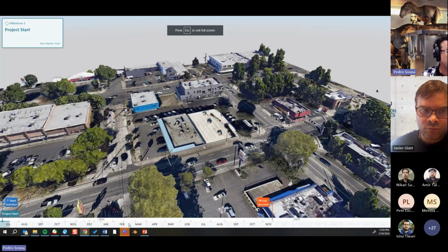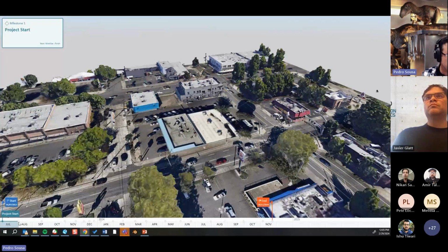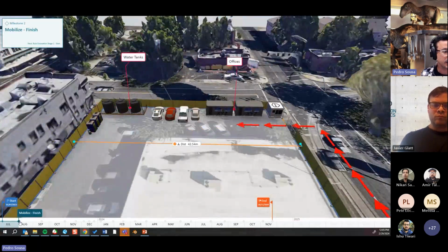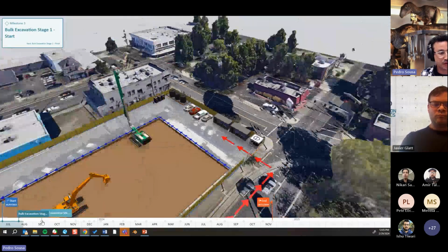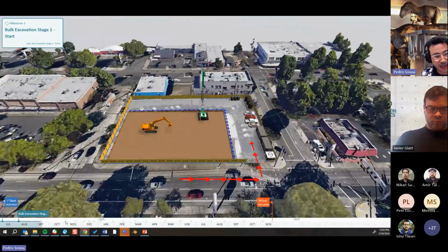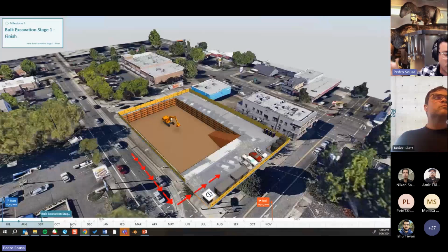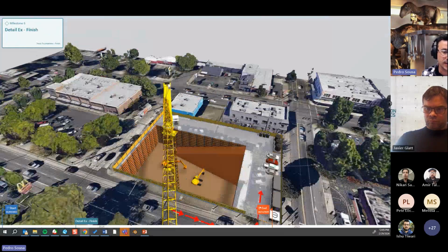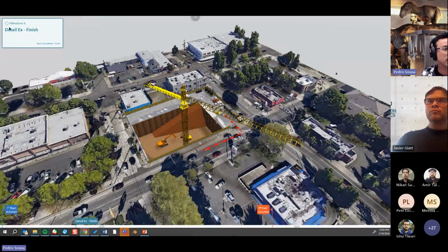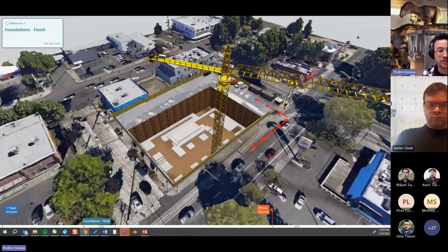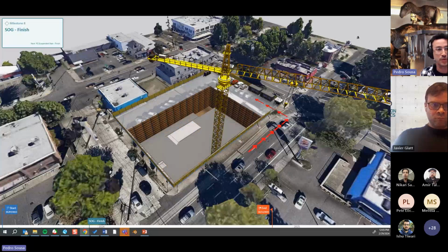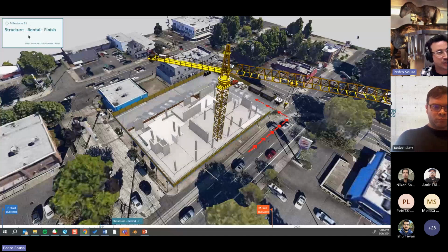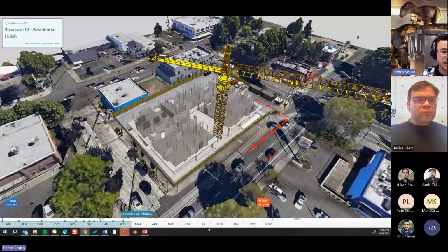But you can see over here in the bottom the timeline function. When you're playing, you can see it highlights the milestone that is active at the moment, and you can see the distribution of all the milestones coming next and where they are in the sense of the progress of your construction site. You can see the start date over here and the end date over here as well. And over here on the top, you have a different view of the milestone command. Before, we were using the same milestone manager view over here on the top, but we changed this to the side where you can customize it a little bit more.